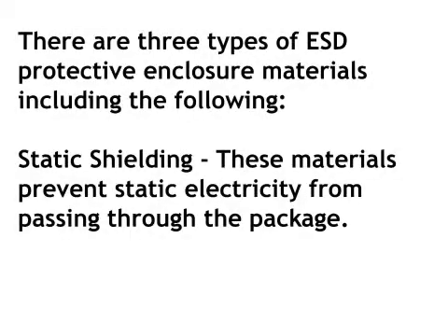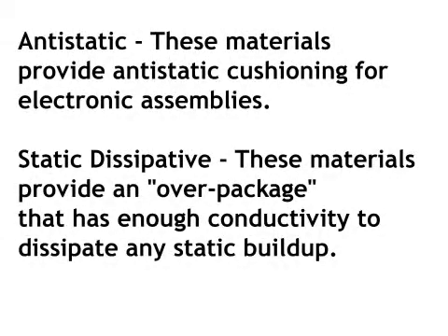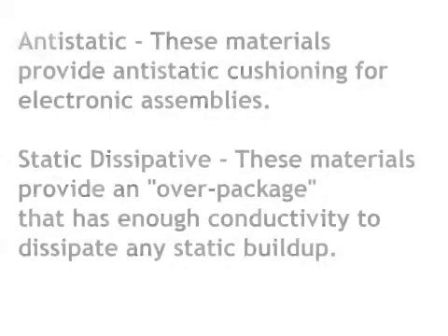There are 3 types of ESD protective enclosure materials, including the following. Static shielding. These materials prevent static electricity from passing through the package. Anti-static. These materials provide anti-static cushioning for electronic assemblies. Static dissipative. These materials provide an overpackage that has enough conductivity to dissipate any static buildup.